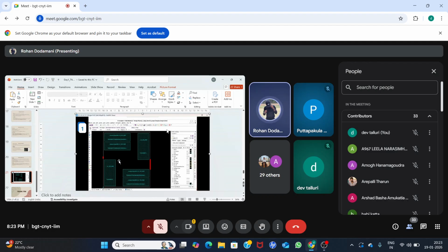First we separate the input ports and place them on side one, and the output ports are placed on another side, side three. You can see the space between the two squares: one is the core area, one is the die area. Between them we place the IO ports. I will open the tool now and show how the floor plan looks.